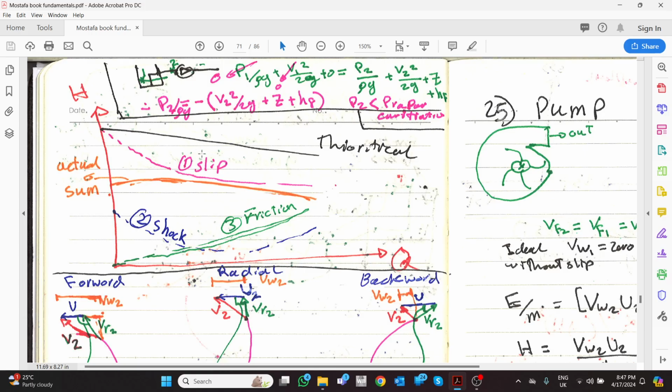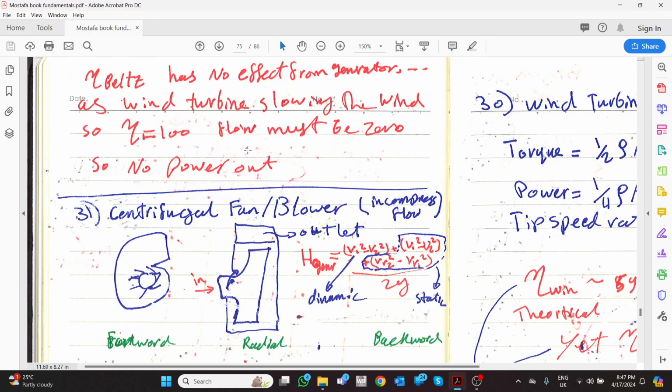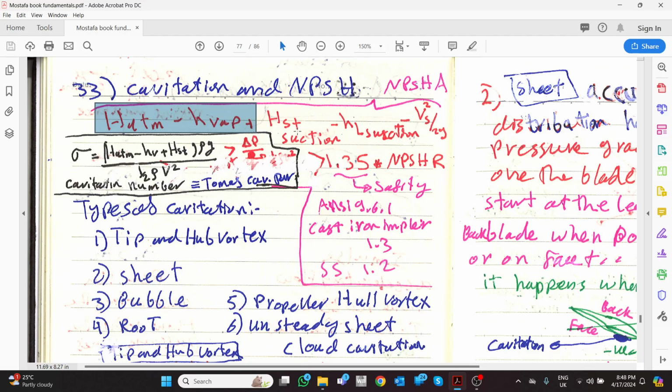It is the pressure before the pump. So static plus pressure, of course with minus, always minus. The static will be in minus because it is suction. Maybe the tank is above the pump, so the static will be in plus, by the way. Okay, so static minus the friction minus kinetic. It is the pressure at the suction.